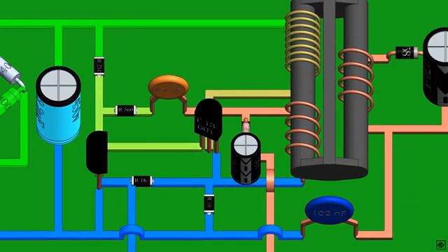Now, this current passes through the 2 megaohm resistor to the base of T1, turning it on. This transistor isn't fully turned on because of the resistance, it turns on partially. Due to the partial turning on of the transistor, a low current passes through the primary winding of the transformer. This induces a low voltage in the auxiliary winding. The induced voltage now charges the capacitor, and then the capacitor fully turns on the transistor.